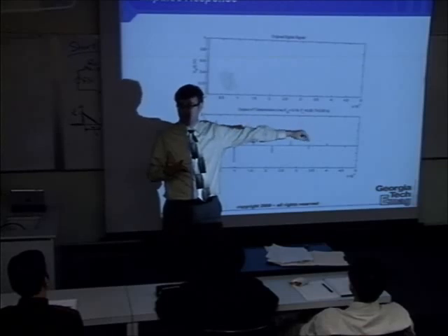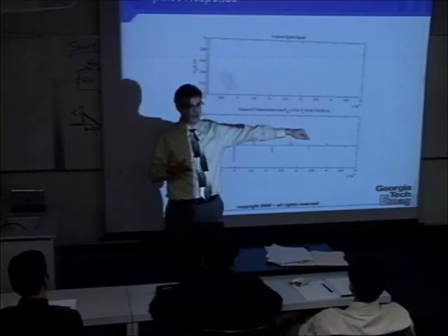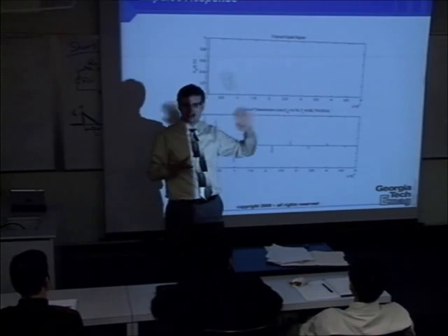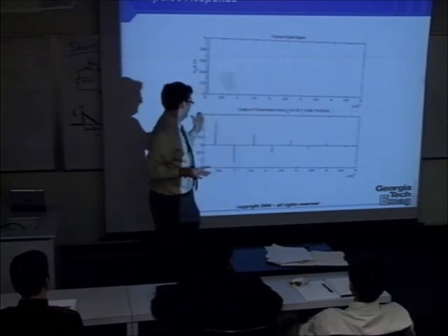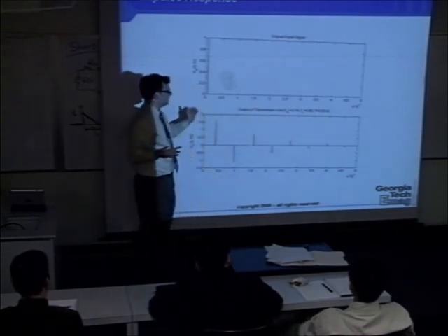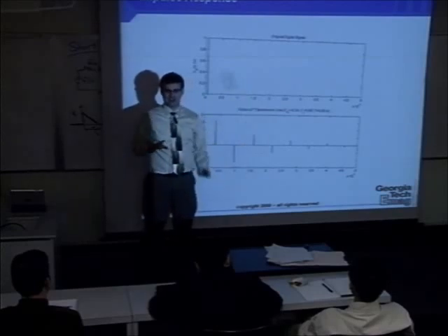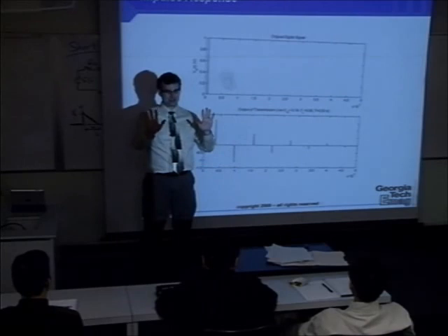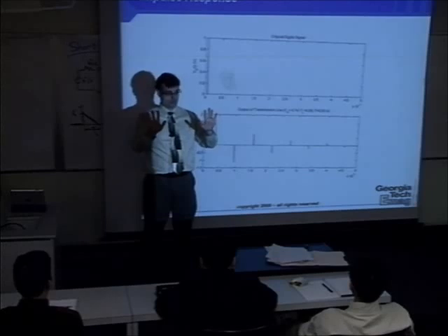This is a linear time invariant system. If I want to put a Gaussian pulse on the input, how do I figure out what the transmission line output will look like? What do I got to do? I got to take my impulse response and my Gaussian pulse and do what with them? Starts with C. Convolve them.